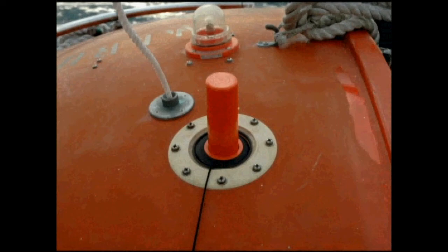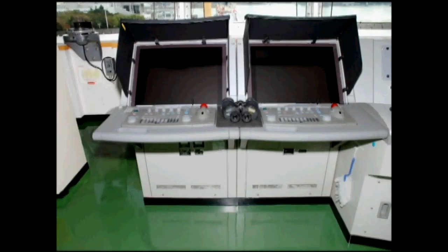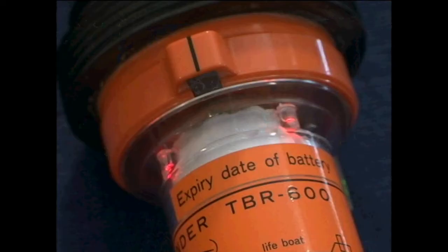When operating a SART on board own ship or in the lifeboat, SART should be fixed with the radome up in a holder or lashed to a handrail with a rope. When using the SART, remember to switch off own ship's radar. This is necessary because the SART might respond to the high signal level of own ship's radar, causing the indicator LED to light up. Detection by the search radar will be unknown, while sapping the SART battery of power. Continued use of own ship's radar may even cause the SART to fail.